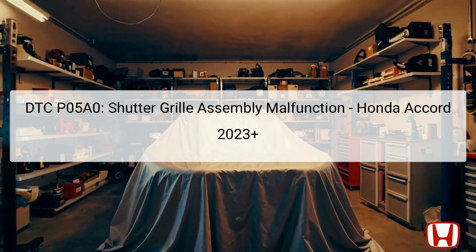The shutter grille is primarily responsible for controlling airflow through the vehicle's front, enhancing aerodynamics, engine cooling, and fuel efficiency. It achieves this by opening and closing based on engine temperature and vehicle speed. The shutter grille is generally located at the front of the vehicle, between the bumper and the engine compartment. The malfunction leads to the PCM storing the error code, triggering related warnings or issues with vehicle performance.